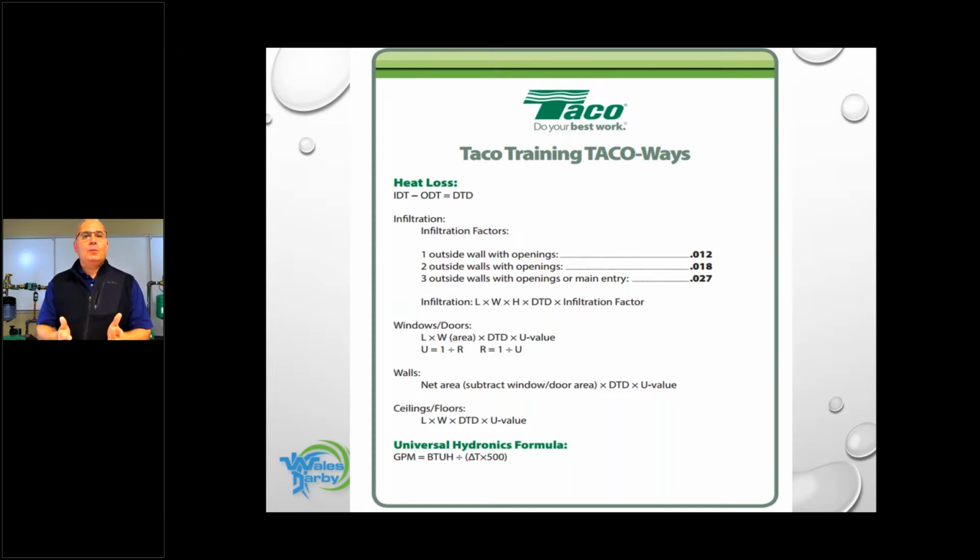So let me explain why I asked that question. All the heat loss programs are going to use what's called an ASHRAE standard. And even if I was sitting here in New Jersey doing a design for Wisconsin, I can go into that program, find that area, Wisconsin, or whichever is the closest, and it'll tell me what the average coldest day of the year is in that area.